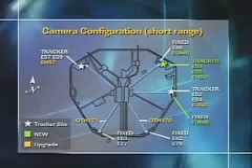For the short-range trackers, next slide, please. This shows where the trackers are located. And actually, this graphic also shows you where some of the fixed cameras are. The short-range ones are within the perimeter fence of the launch pads. They cover from liftoff to about 1,200 feet. Each camera site has 2 35 millimeter film cameras and an HDTV camera on it. There are a total of 3 sites of short-range trackers, and 1 is new for 114.